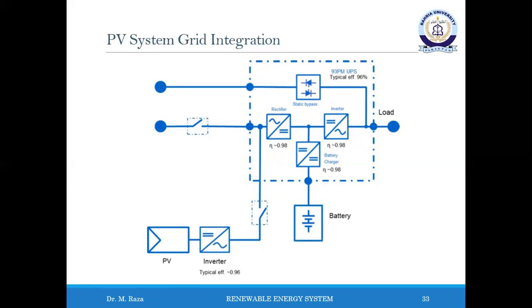Typical weighted efficiency for a commercial grid-connected PV inverter is about 96 to 97%. For external cabling and connections, about 1% losses should be estimated. As a result, approximately 91 to 92% total power conversion efficiency for the PV system can be achieved with this topology.